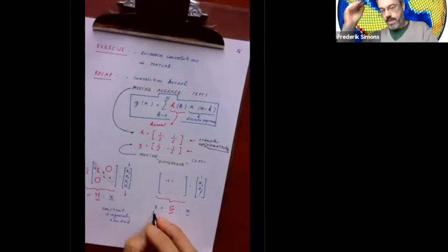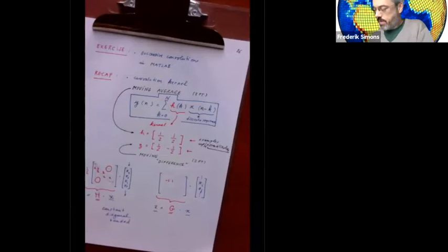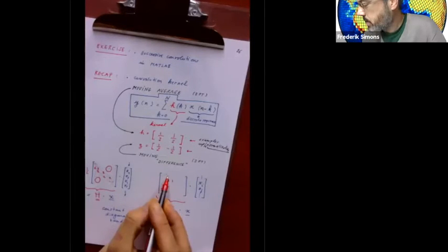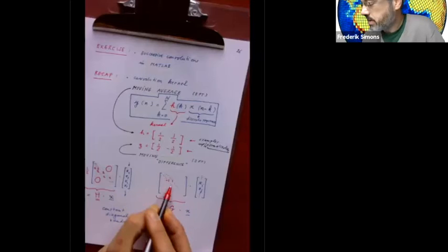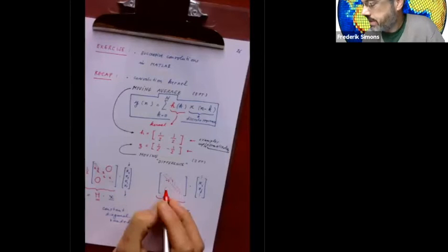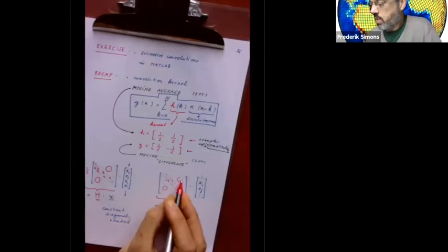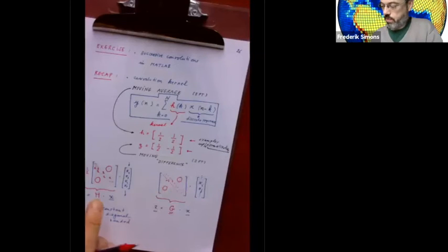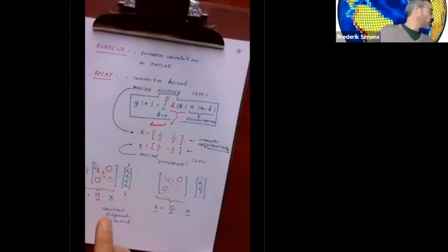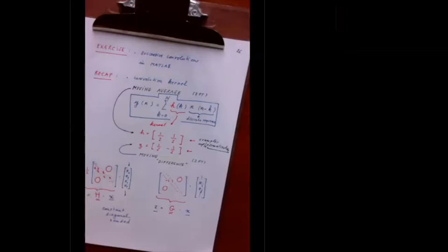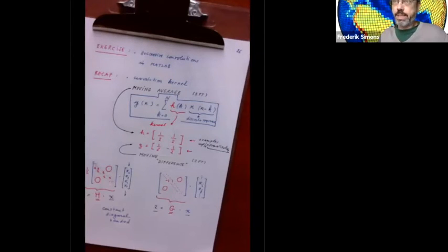Okay. And so a discrete time convolution leads to a banded constant diagonal and otherwise zero matrix operation where the outcome of convolution is just the matrix vector product of what you put in with the response of that system. And the response of that system has, for every row in the matrix, the filter in it, that kernel in it, shifted and copied.